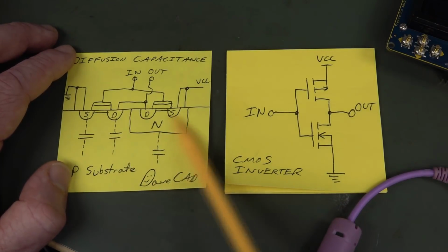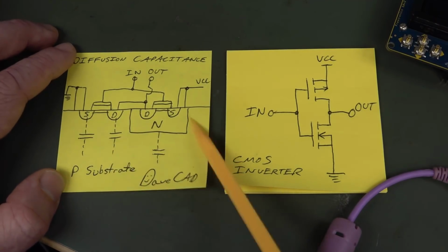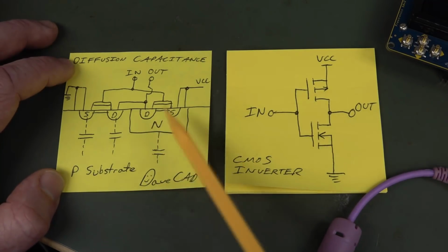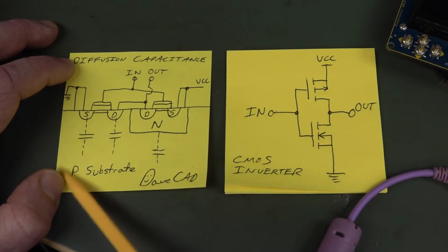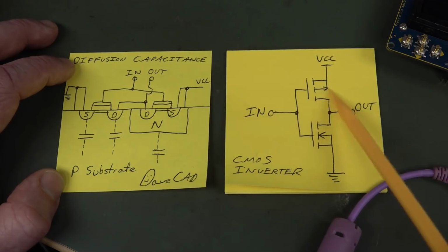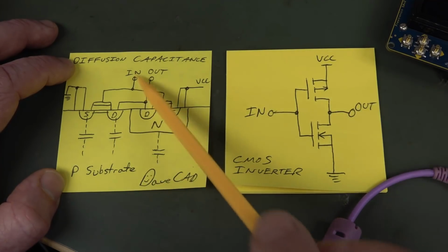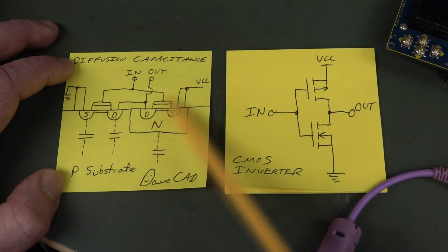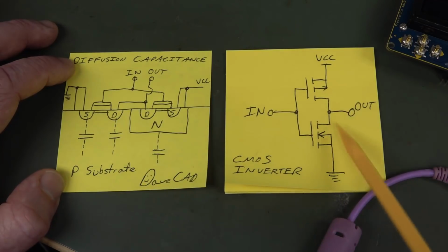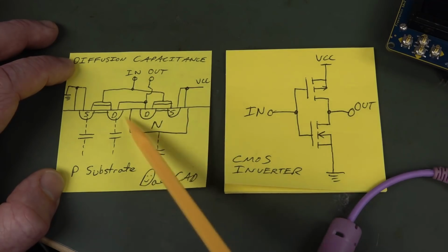But anyway, here's a rough DaveCAD sketch of what it looks like on the silicon, the semiconductor level. Please excuse the crudity of the DaveCAD, I didn't have time to build it to scale or to paint it. Basically we've got a P substrate down here, we've got an N type here, and this is our upper MOSFET up here, and this is our lower one down here, and these are the connections outside. So our input goes into the two gates, I didn't label those, and then we've got our drain, our source, and our drain. Our two drains are connected in the middle like this.